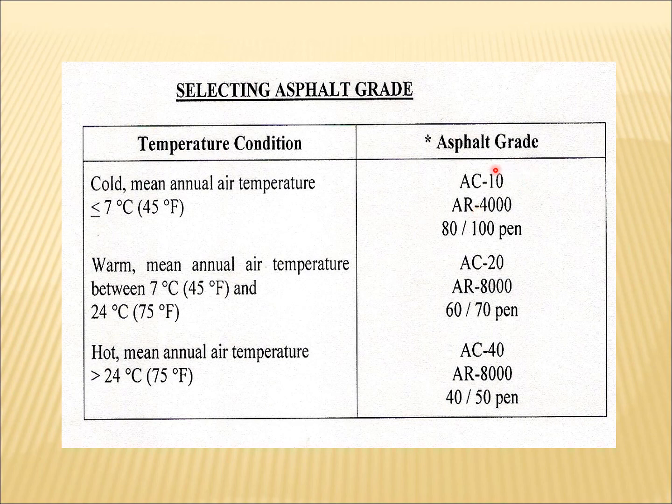And if you just look at this number which is mentioned here, this is basically the viscosity at 60 degrees centigrade in poise divided by 100.